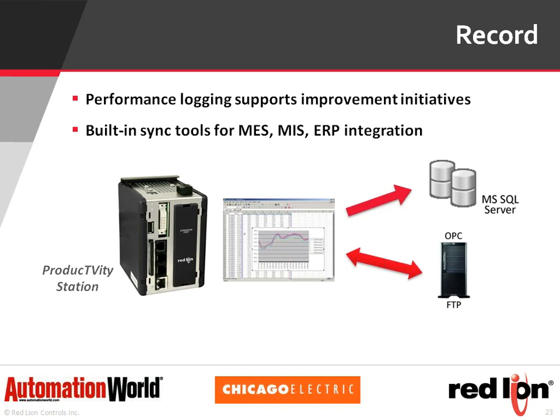You're going to want to log those Andon messages. At the end of the month, you're going to want to run a Pareto analysis. Take a look at the reasons you had machine downtime issues. Attack the top 2 or 3 problems that you've had. So make sure that the tool that you select has those logging capabilities, and also make sure, we want to keep the IT people as our friends, that those tools integrate easily with MES, MIS, and ERP systems. Make sure it integrates into the back end.